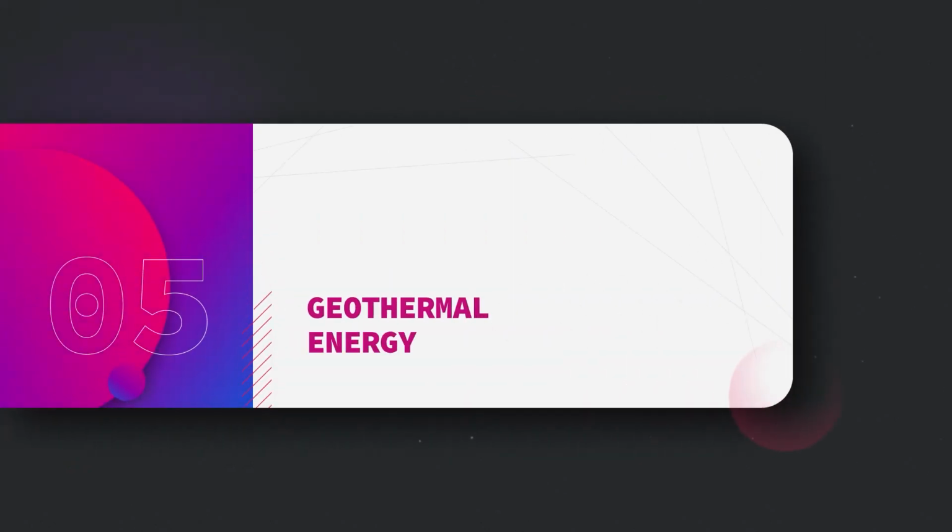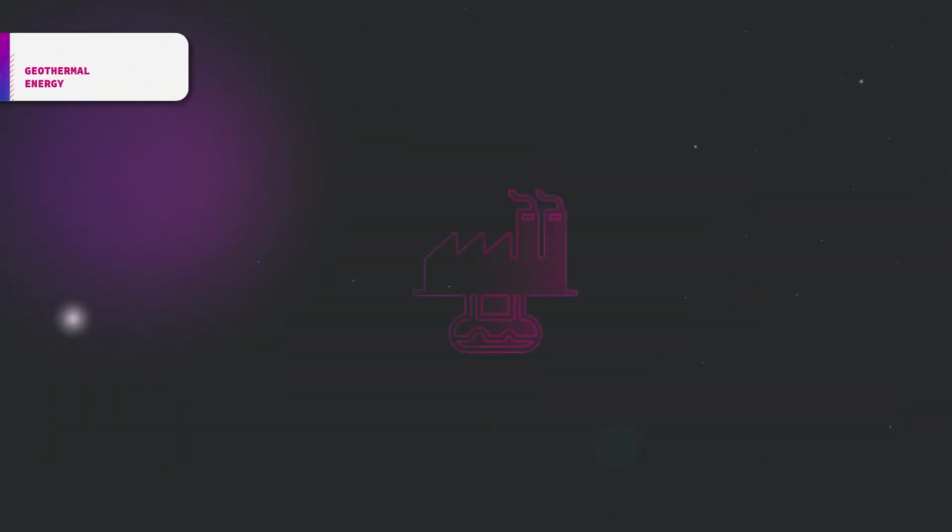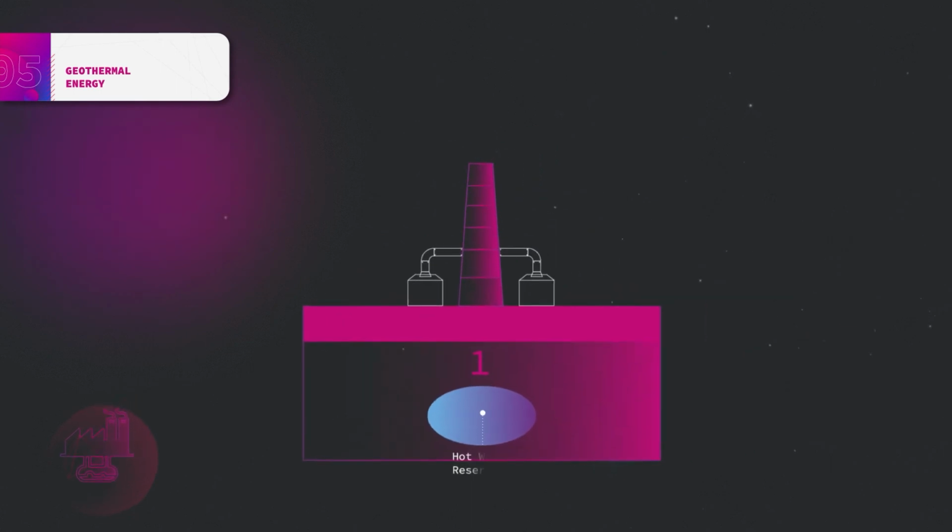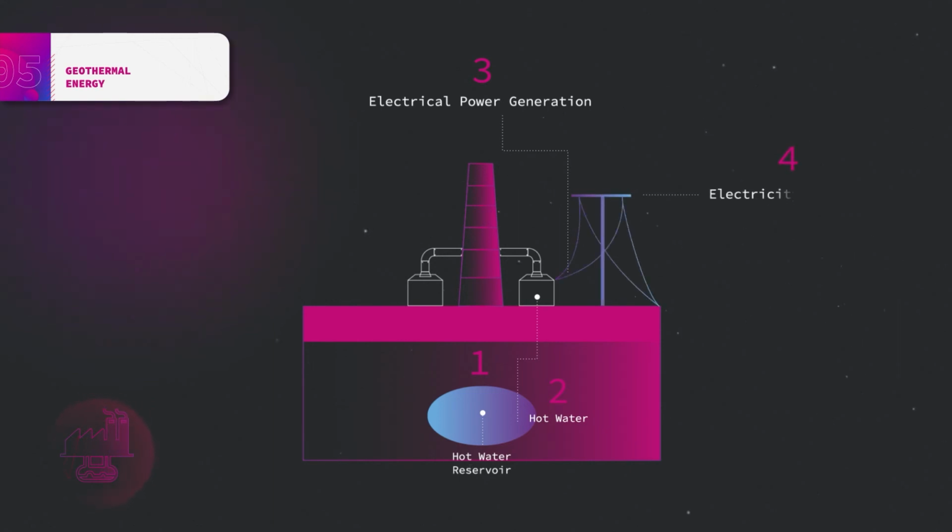The usage of geothermal energy for electricity generation or heating purposes is possible in regions with thermal water existence. A hot water reservoir, known as an aquifer, is reached by drilling, and hot water is delivered to the surface. Using a heat exchanger, the heat is transferred to a power plant. Turbine and generator transform the heat into electricity and feed it into the network.